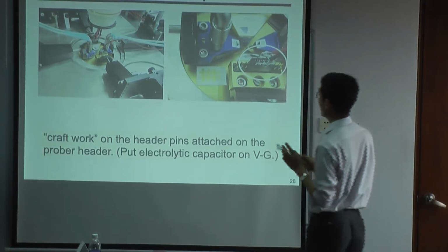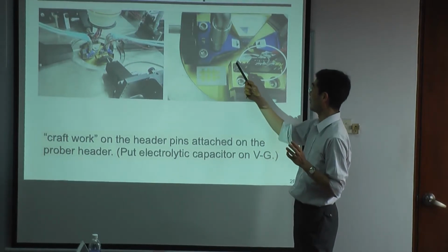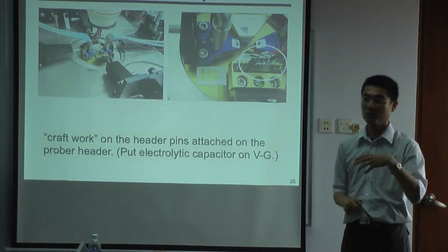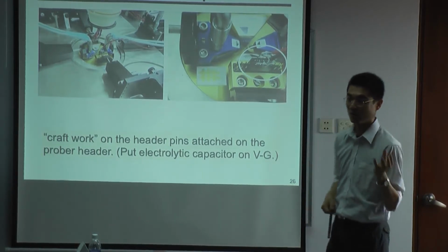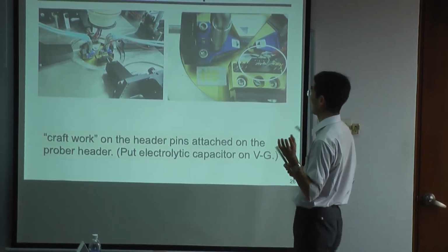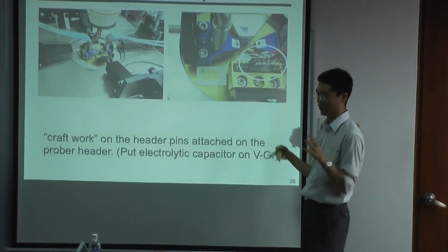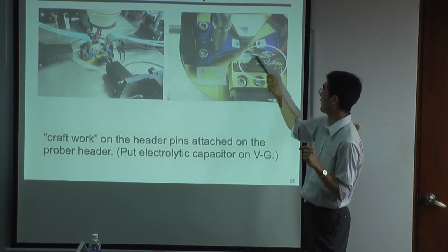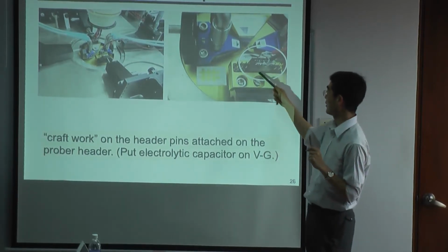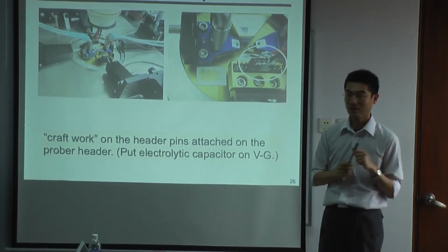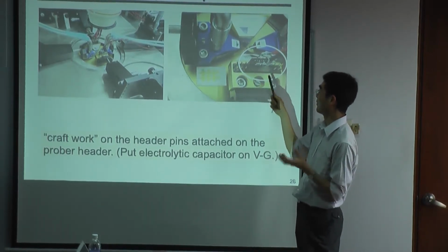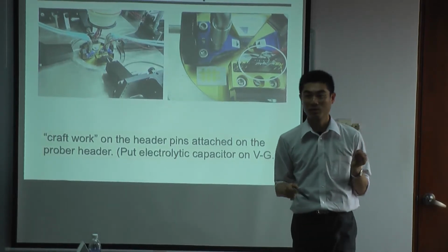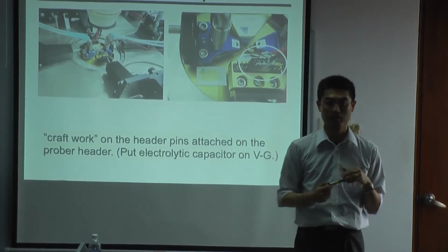And we don't want to directly put capacitors on these probes, because many people use the same probes. So if you want to apply a more stable supply, you have to make these header pins by yourself and do a kind of work to make a stable power supply or stable control pins.